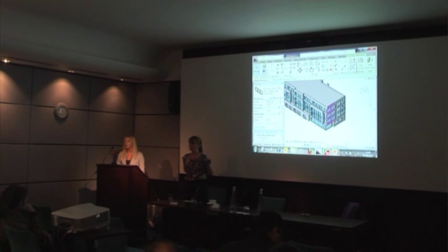Not just from us, but also there's the same documentation produced by Revit and other programs, and say, make these little edits to it and we'll see if we can get a little further. But if they learn how to do it, it works better. I'm going to show you in the second session some ways to query your model inside of IES so that you can see, are there external holes, are there problems that are going to be causing me issues later, and those types of things. So there is a check that you can do that you really should be doing.